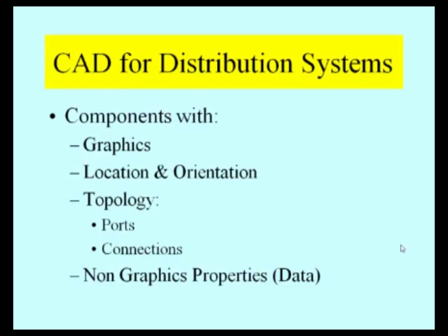Ports. Every CAD system has a port concept, and you've seen it already. Every CAD system has a connection point concept or a port concept. And then we care about locating components in space. We also care about alignment. Every pipe that connects to a nozzle, every nozzle that connects to a nozzle, needs to be aligned with the nozzle too. Not just connected, but aligned with it.